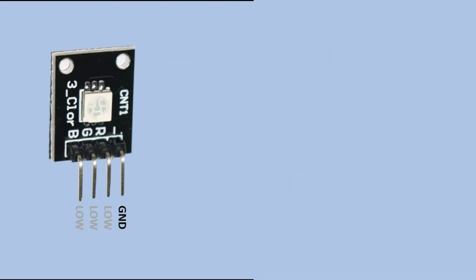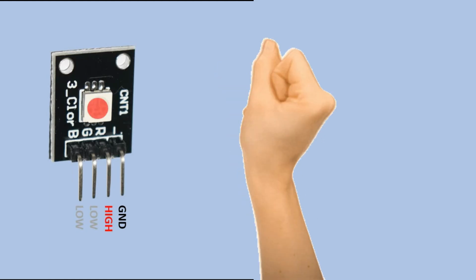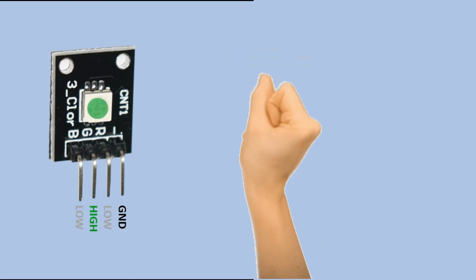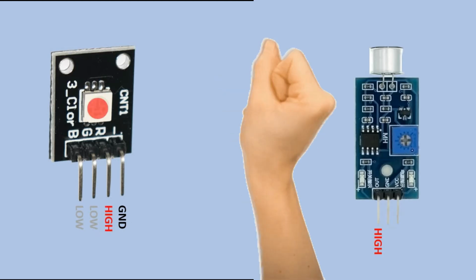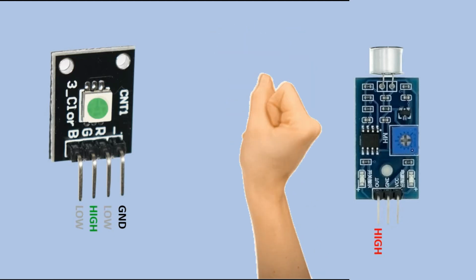What we want to do with interrupts is to introduce an external event, e.g. a finger snap, which will not affect the interval with which the LED is blinking, but would change the color of the LED. So this is what we want to achieve. We do it by detecting the snap with a sound sensor. Each time we detect it, a high signal is sent to the interrupt pin that kicks the interrupt and changes the color of the blinking LED.